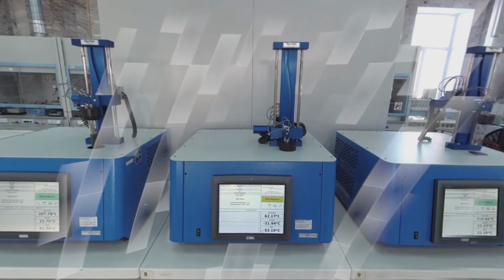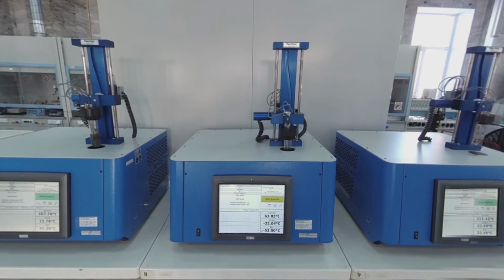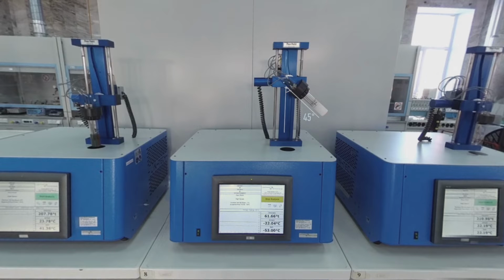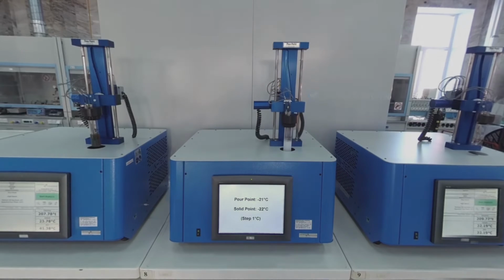Here, the temperature is determined at which the oil loses its fluidity. The sample is gradually cooled down to the temperature at which it becomes non-fluid in an inclined glass tube. This indicator is of importance for shipping and for filling up the equipment with oil under low ambient temperatures.